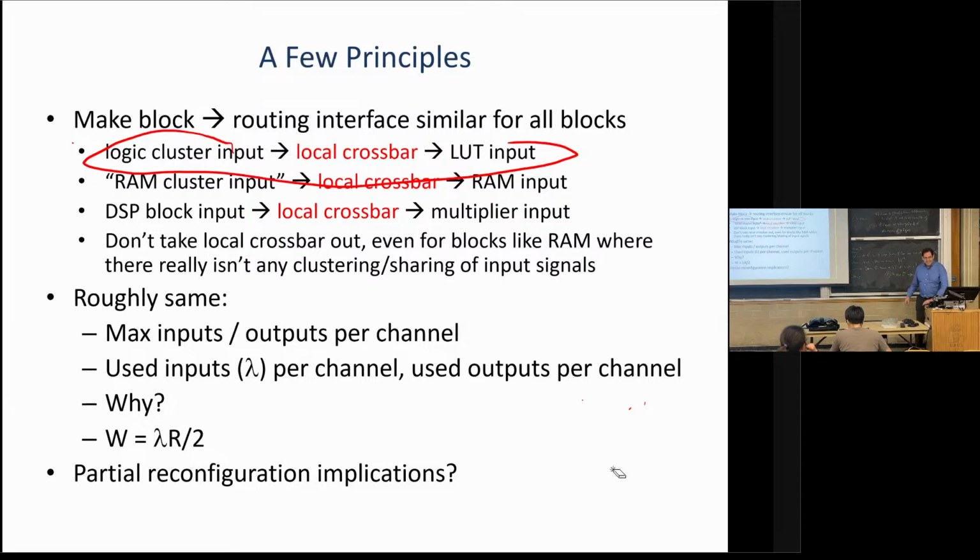So they don't appreciate the brilliance of it, because you've just taken away a problem they never saw. I noticed that this is an architectural change that had a bad effect on partial reconfiguration. Is it often the case that architectures try to plan for partial reconfiguration? It's not important enough currently that it's the main thing you do. But as long as your configuration circuitry can rewrite part of your design without disturbing the other part, then you can basically do partial reconfiguration. So it's not a high cost to support it. It becomes a CAD problem of how you make that usable by people, which has been the harder problem.